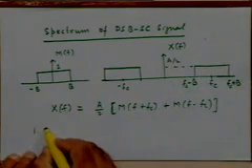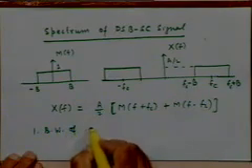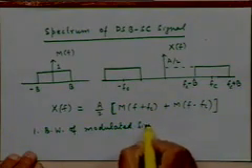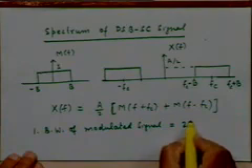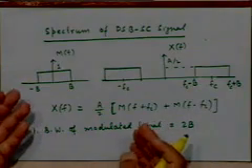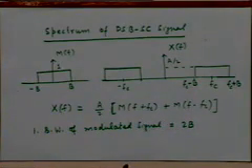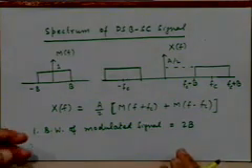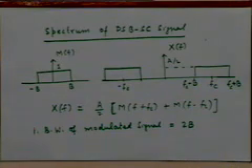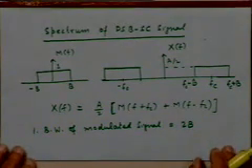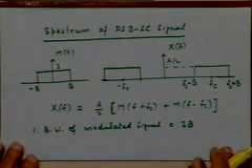So the first thing that we note is the bandwidth of the modulated signal is 2B. So actually your modulated signal has a larger bandwidth than the message signal. Is that a nice thing or a bad thing? From the bandwidth conservation point of view, it is not very nice. Now what does it mean? It means that perhaps we are transmitting more information than is necessary to transmit. And can we see that happening? Can we see how it is carrying more information than is necessary?